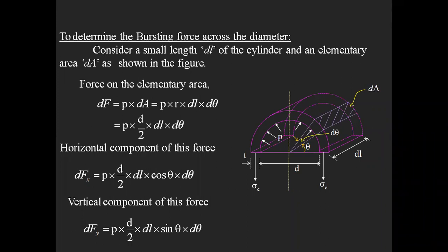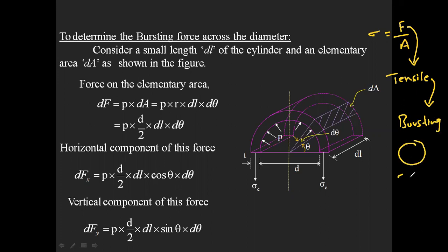So sir, what do you mean by bursting force? Here, when you are going to calculate your circumferential stress, it is going to be developed only based on the force. Why? Because we all know stress is nothing but what? Stress is nothing but force by area. Here, what force is acting? The force is tensile in nature. This tensile force is in the form of bursting. Bursting means it divides the cylinder into a number of pieces. Okay, that's why it is called a bursting force.